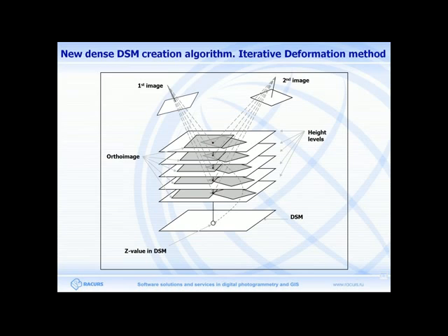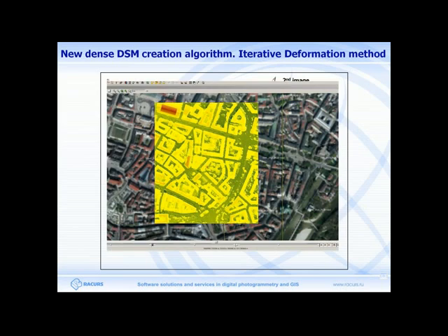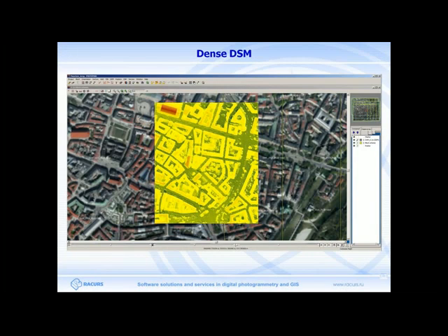For the best result, it is recommended to have at least 4 overlaps at all points where the surface is calculated. There are special parameterization functions and elements of the theory of pattern recognition in creating point clouds for the best description of walls and buildings.